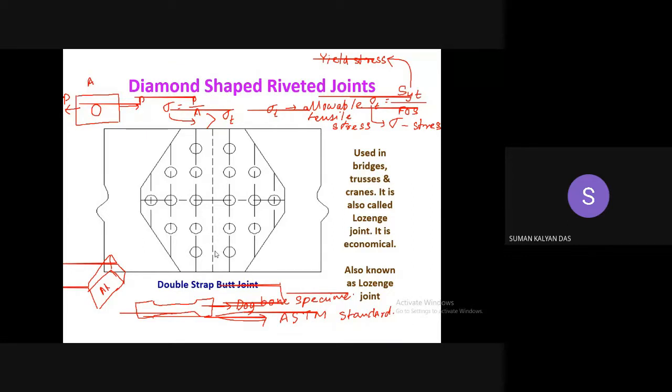the load and displacement that you subsequently have to convert to your stress and strain. For stress, you need the area. So area is calculated, and load by area gives you the stress, and displacement by the original length of the specimen gives you the strain. That way you get the stress and strain curve, and from the nature of the stress and strain curve, you can get the yield point, and from that you can get the SYT.